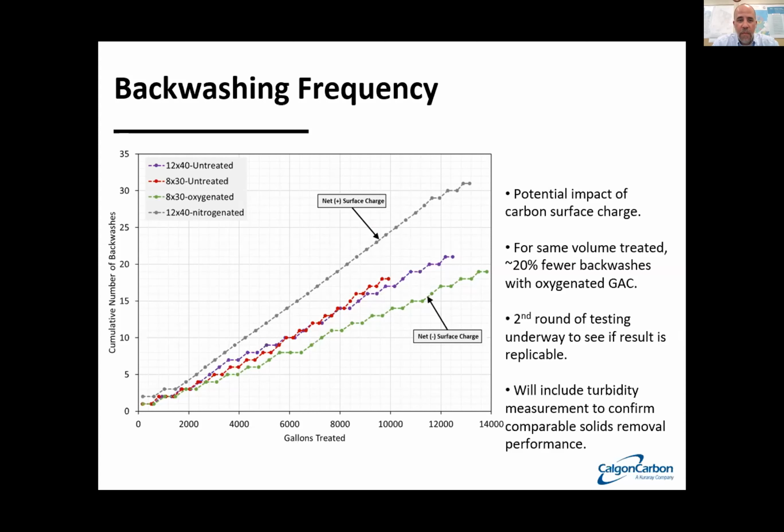And from a particle retention standpoint, we now need to go back and look at the turbidity. This is not something that we examined in great depth in the first part of the study, because we need to confirm that all these materials are providing the same particulate removal, because that is, from a physical standpoint, the goal of one of these systems.